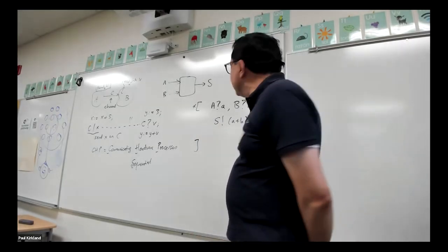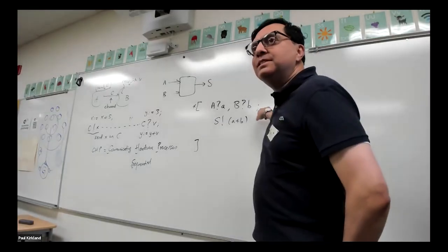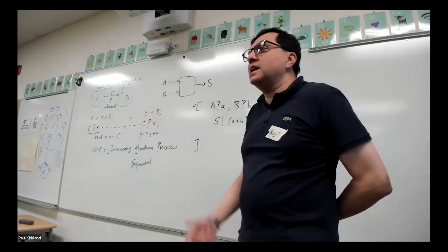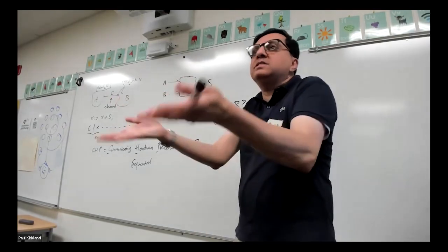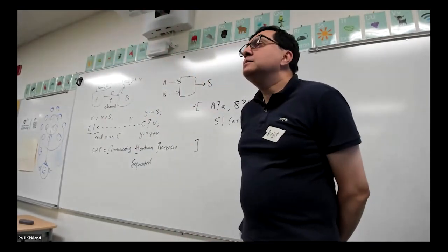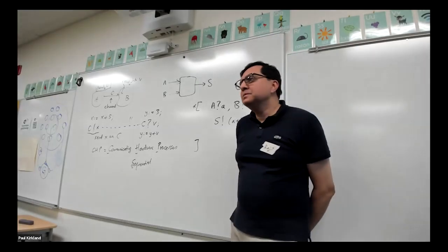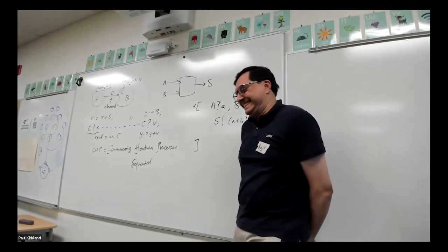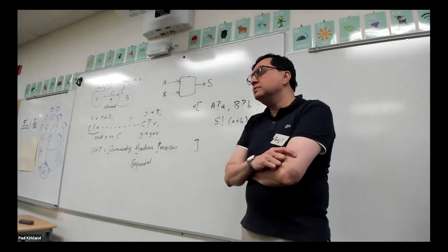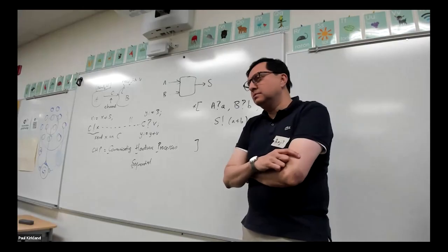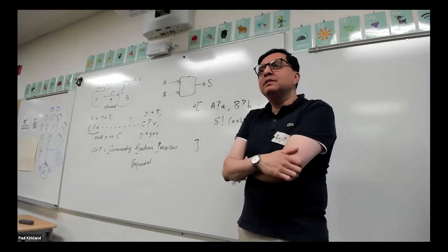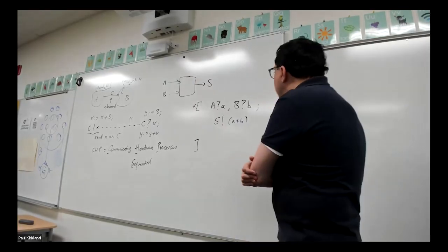Is it a pure combinational block? No, this is not going to be combinational because there's a semicolon here. So you have some kind of state element, right? There will be some state-holding variable. Yes, exactly. A circuit that even waits for two inputs to arrive is a state-holding element. I want to make a comment to everybody, repeating what you said at the beginning: try to start thinking at this high level of abstraction, and a lot of the rest will happen automatically with his tools. That's right. That syntax ensures that it's waiting simultaneously for A and B.